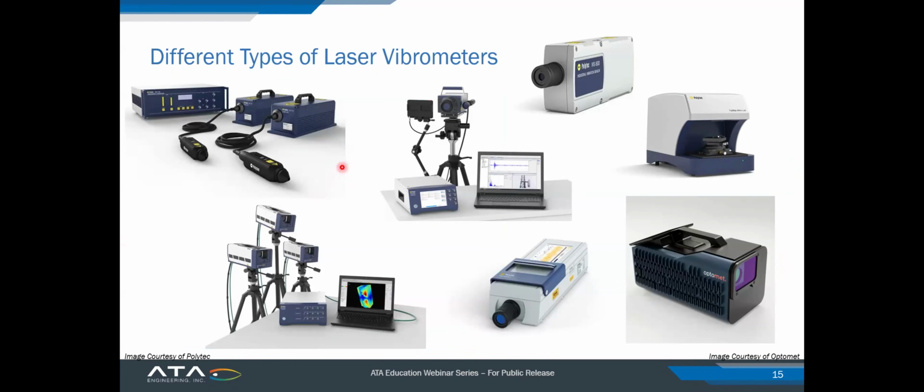So as I was mentioning before, if you're more concerned with single point testing, you might want to use just one of these single point vibrometers in end of line testing, or you can create an array of all of these laser vibrometers if you run a very similar test every single time. But then we also have our single scanning heads. So these are very useful when you need to measure your out of plane responses. So displacements, velocities, or accelerations on your structure. This could also be used for non-destructive testing we're talking about.